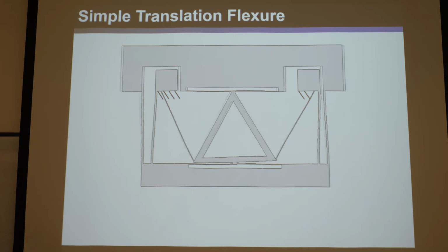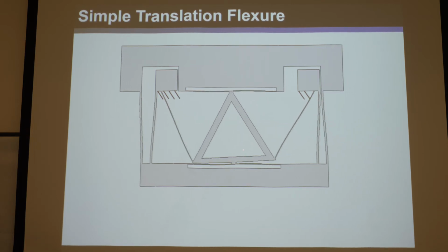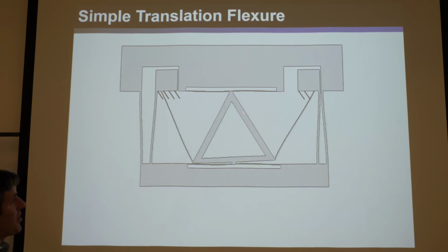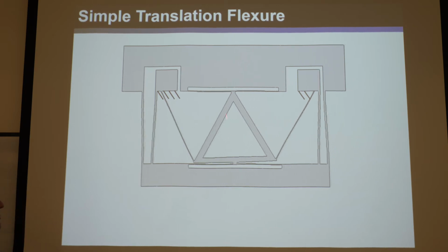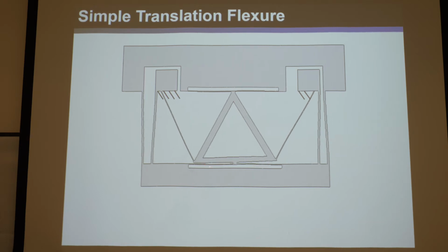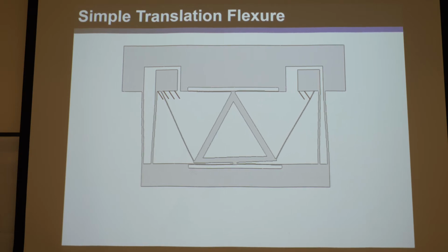And of course, all these designs I'm showing you are interconnected hybrid. Basically you add another symmetric rigid body, hollow out the mass, cut the triangle out to hollow out the mass. So this is supposed to be like a rigid truss. It's just a big rigid body. We added this flexure and these two flexures and this flexure here. Okay, what this does is, again, it doesn't increase the footprint of the system.